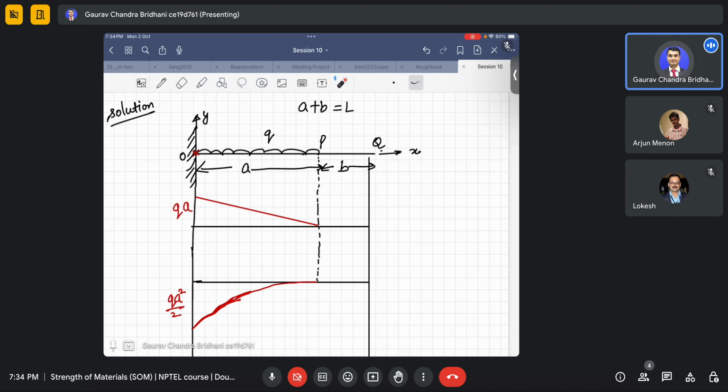Suppose in a determinate structure it is a 2 point bending, or the points of loading may not be placed at equal distances. It could be a 4 point bending with different distances, not an exact 4 point bending. There you can't use the q equation because you don't have any q. What I meant is a scenario where you have a beam like this, with one load here and another here. For this case you can't use the q equation. You have to go with the deflection.